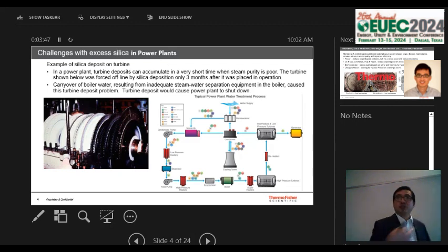During startups, you could cause turbulence, which may disturb some of the silica scale in your feed lines and your turbine feed wall. So you want to monitor somewhere here too. You also want to monitor what's in your condensate. Maybe, like in this instance, some water got into your steam, and you can see that from the condensate by monitoring there.